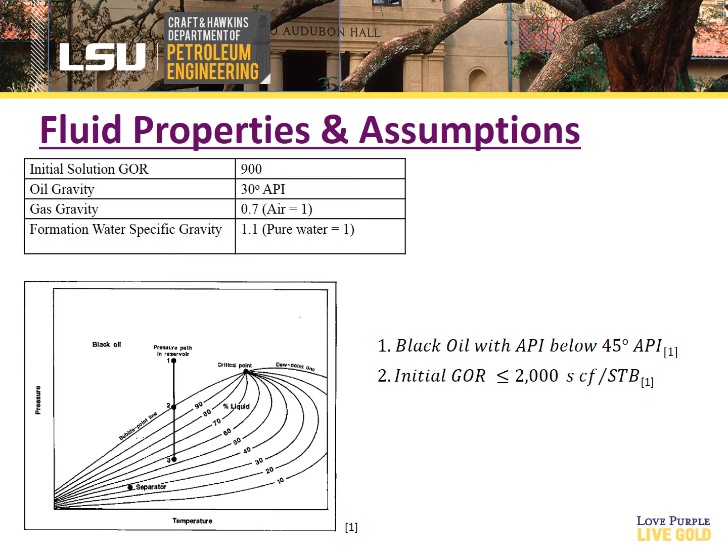Using the black oil model, the missing data obtained was the viscosity, oil volume factor, and total compressibility. Also, additional assumptions made were anisotropy equal to 1 and relative oil permeability equal to the reservoir permeability. In addition, calculations were done in order to obtain other missing data needed. These correlations and calculations were done using Appendix B in our textbook Petroleum Production Systems. With this data, we were able to conclude on the fluid model that we were going to use.